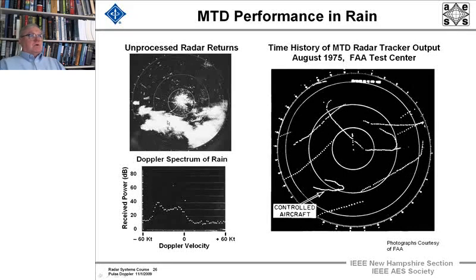And this is the analog PPI display within a minute or two. I mean, the rain runs 20 miles an hour. This was a very, very heavy rainstorm in August of '75. It was about the toughest one, and we sent a test single-engine aircraft up, and it was essentially unity blip-scan ratio in the test.